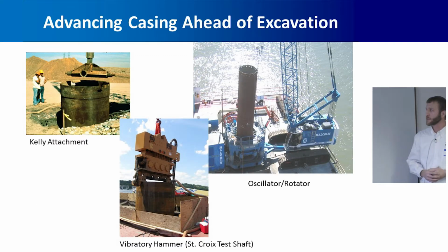So there are different ways of advancing a casing. You can just twist it in with a Kelly bar attachment on a drill rig. You can vibrate it in with a vibratory hammer. That's what they did at St. Croix. That's probably, I guess, what I expect at Red Wing. Kind of the most aggressive way